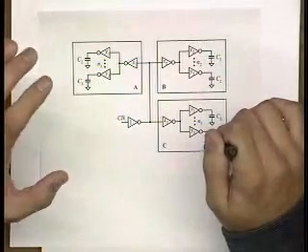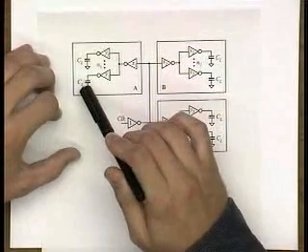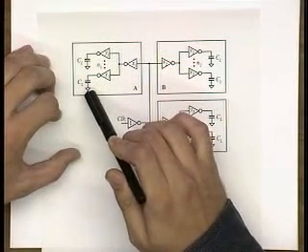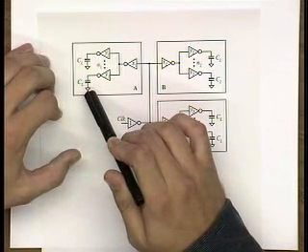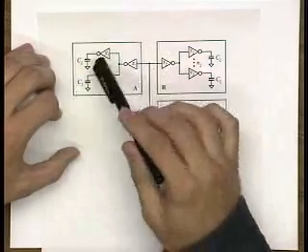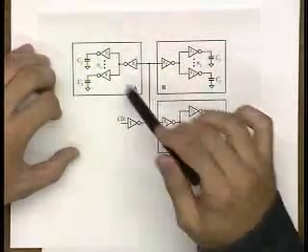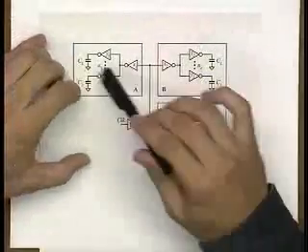So you assume that each of these buffers can really reliably drive only a certain number of flip-flops. Let's say CL was 16 in this case, so maybe that's about 30 flip-flops or so. If you drive more, then you have problems with slopes and things. You don't want to do that. And due to varying complexity, you have different sizing factors over here. So now let's assume that you have finished designing all of these blocks.